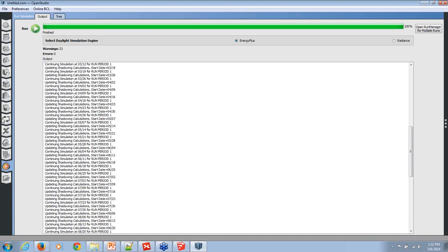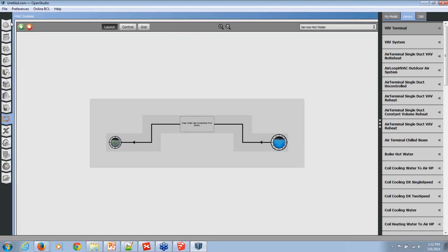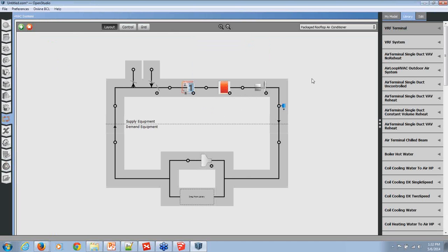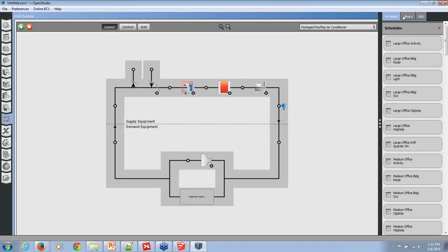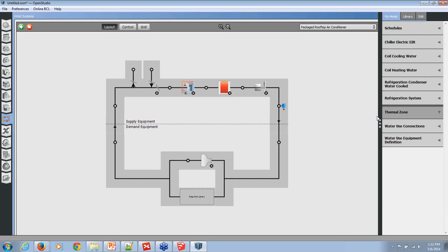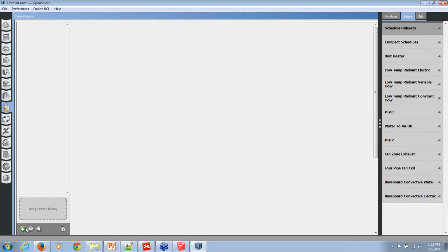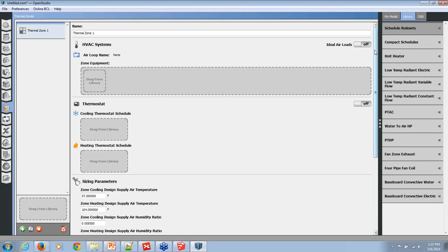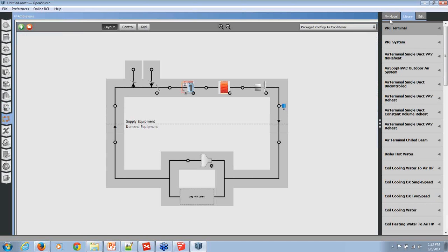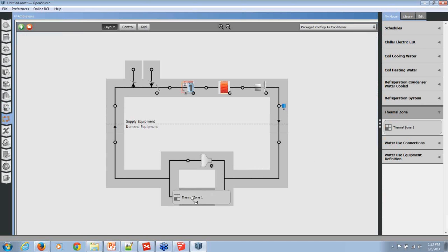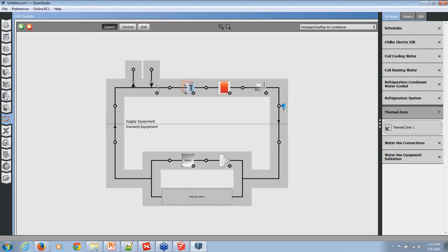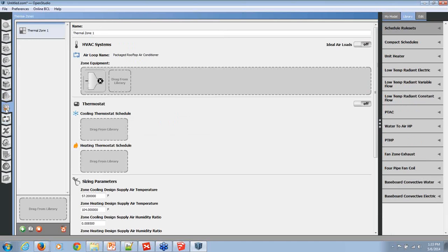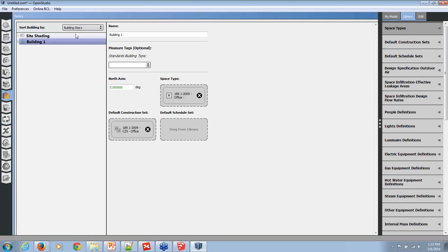We have nothing like that, so we'll very quickly add an HVAC system to this. And again, in the interest of time, I'm going to make it very simple. I'm going to just throw all of our thermal zones. We'll create a simple thermal zone. And we will then attach that thermal zone to an air system by default. I know these are things that, again, you have to do just to get a model to work correctly. And then we'll go over here and we will take our spaces and assign them to that thermal zone. So essentially we're building an HVAC system here.